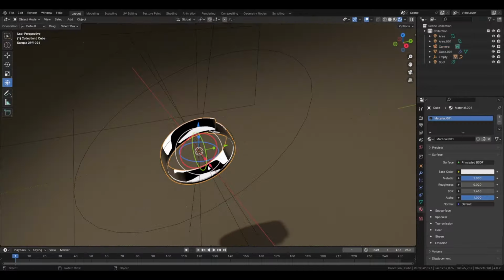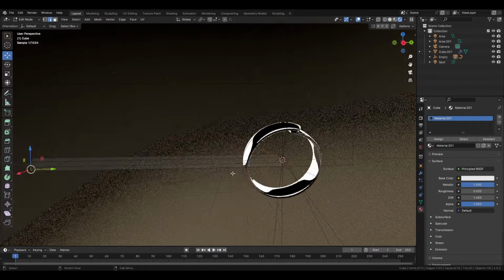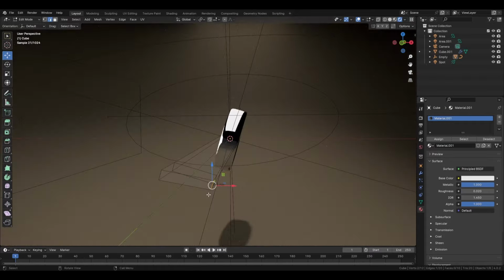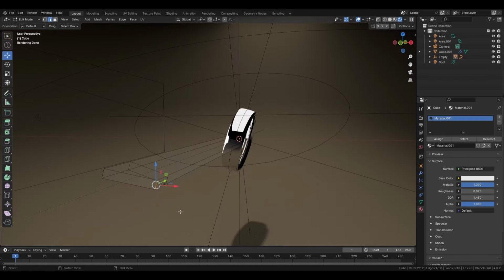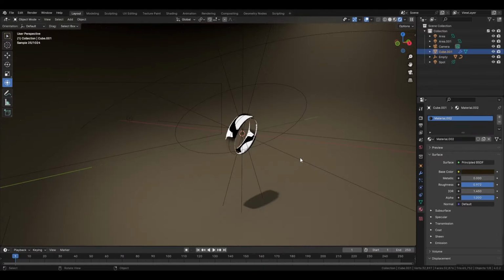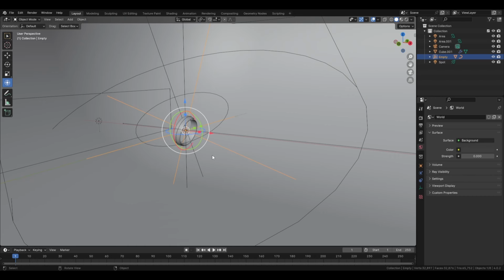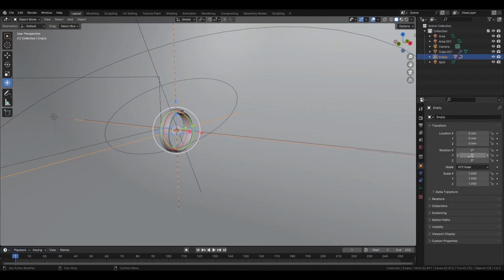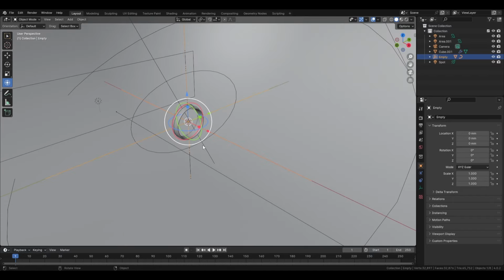If you want to change the thickness or everything of your ring, you can still go in edit mode and change this. If you have something much more complex here and that you want to actually be able to still edit it flat and not like this, there is a trick. So actually, you will need to have 2 empties. So you're going to reset this empty, this one, so you can do all transform. No, so you can go back here and put it straight again, like this. And you can create another empty. So actually this is here, okay.